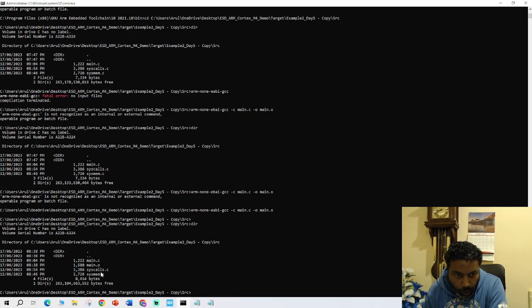This main.o is not target specific. It doesn't mean that it will run on that particular STM32, because when it generates machine code, it doesn't target one particular microcontroller, so it generates for different architectures. So now you have to generalize that for your STM32 series. To do that, you have to go to another side, but I think we are going a bit longer here.